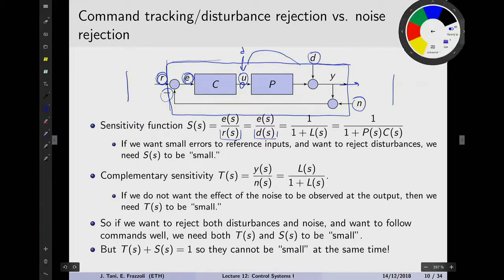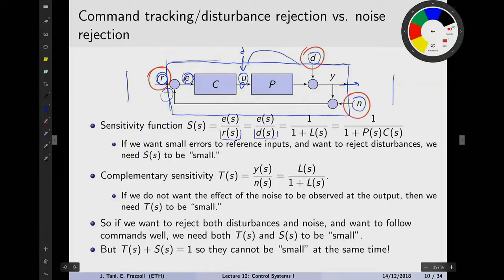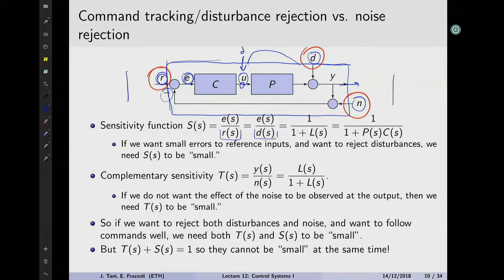The inputs of this block are the reference signal, the disturbances, and the noises, which are often called the exogenous signals. That is everything that is just thrown at your system, right? We get to choose one, we don't get to choose the others, but this is the input to our feedback problem. And the output is typically the output of the system, or actually even better, a measured version of the output. But anyway, if we choose any pair of signals, we get a transfer function.